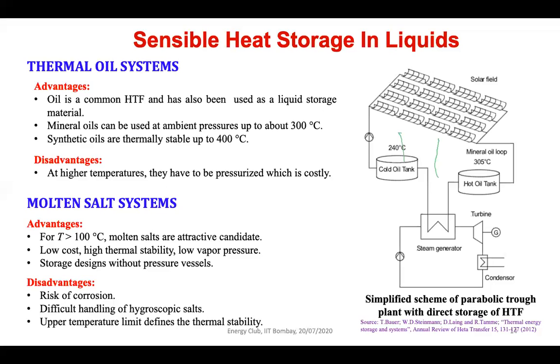So something like up to 400 degrees centigrade, depending on the oil, you can use it in a single phase. But as oil cannot go into two phase, it will burn. So the limitation is around 350 to 400. Beyond 400, you cannot use oil. So there you have to use some other heat transfer fluid.